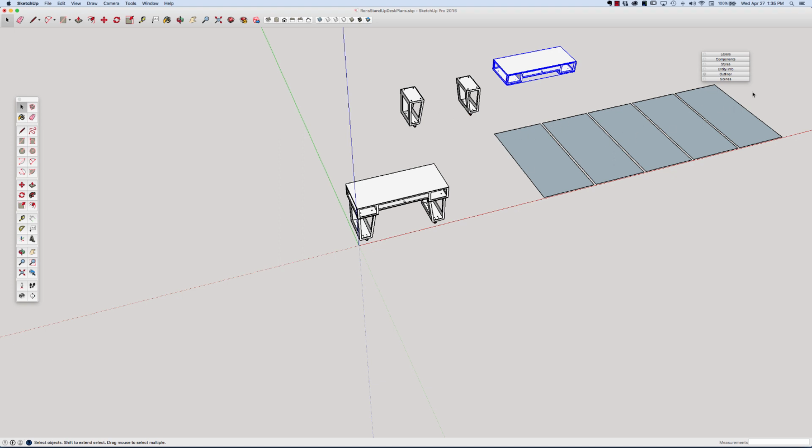And this is like a jigsaw puzzle. I will be moving pieces around and creating a visual cut list so that it'll be printed on the plans, and anybody who has it can at least see my suggested layout of the parts. So I'm going to now take the top, and I'm going to hit explode, and that will get me into that group. And so I'll start with the biggest part.